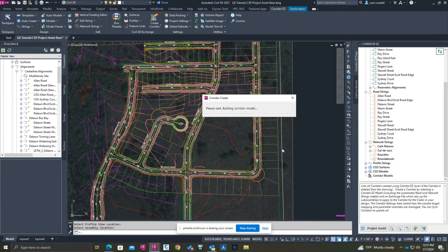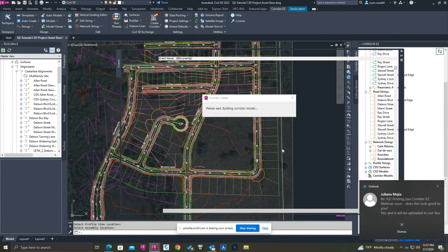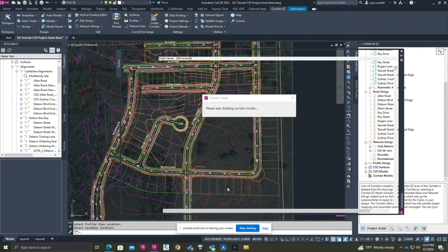Now the assemblies it's creating, it takes the template that we've used, applies the subassemblies and constructs the assemblies, and the assemblies that it makes are for each region that you're building out. So just keep in mind that there's a library of assemblies that is going to drop in, and because it's region-based, if you find a certain region that you need to tweak, you can edit that assembly or subassembly to make that tweak in one area without affecting the entire model.